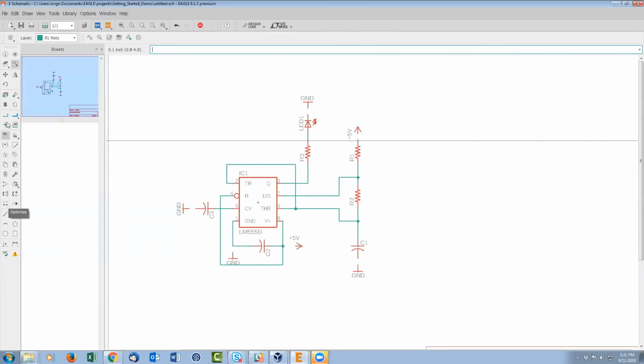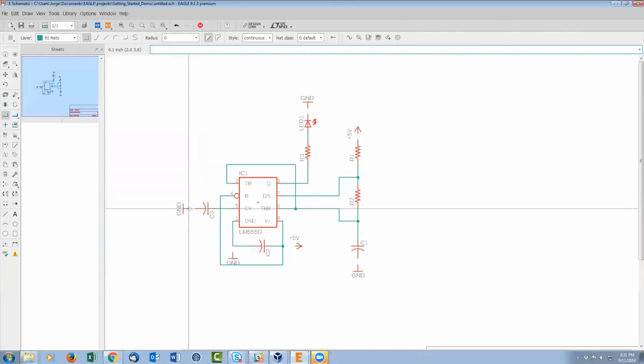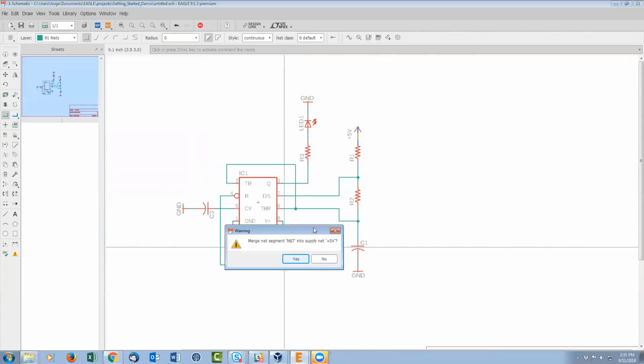Okay, so again, we use a net command to connect them. Please realize we're using the net command to define connections. We prefer if you stay away from the wire or line command for your connections. Always use the net command. Line now makes it clear that it's just an artistic tool. But before, sometimes users would use that one and it doesn't work the same. It doesn't connect things properly. So your connections are always made with net.